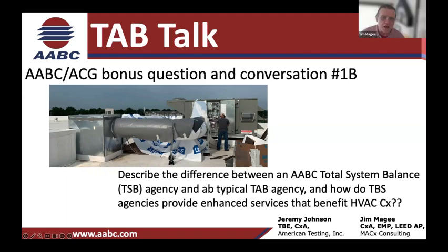I'll tell you what I like a lot, if it's still being done, and I'm sure it is: a hydronic checklist and an airside checklist for preliminary checkout on your TAB project, whether it's ready or not. Sure. That's a really good system. TAB readiness checklists are huge.